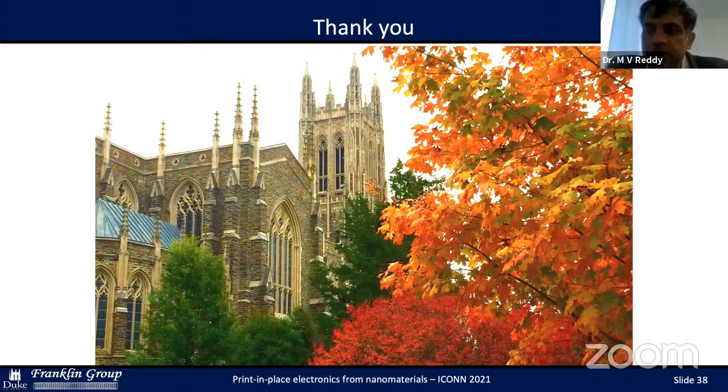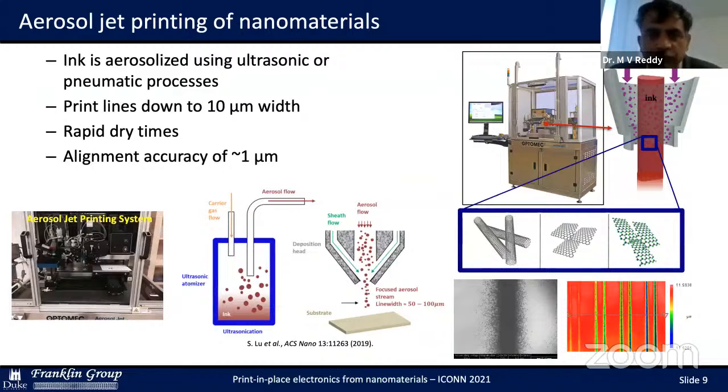Since I am a battery specialist, suppose, for example, I use a ceramic powder of 15 micrometer, with some 10 weight% of the polymer binder PVDF, and some carbon. Is it possible to make it into what they call ink? Yesterday, some people asked me about ink printing. I told them it is difficult because of the nozzle; your ceramic particles get stuck there. With your technique, something is different. I know aerosol involves particles being sprayed, so with the liquid type, is it possible? I just wanted to ask out of curiosity.